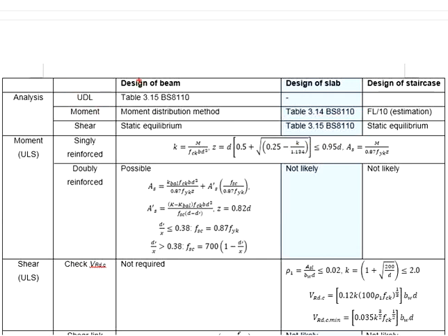And then, if the member is a continuous member, you use the moment distribution method. The moment distribution method only gives you the support moment, which is the fixed end moments after redistribution, both sides cancelling out each other, and this will become the internal moment to be taken by the continuous beam at the support.